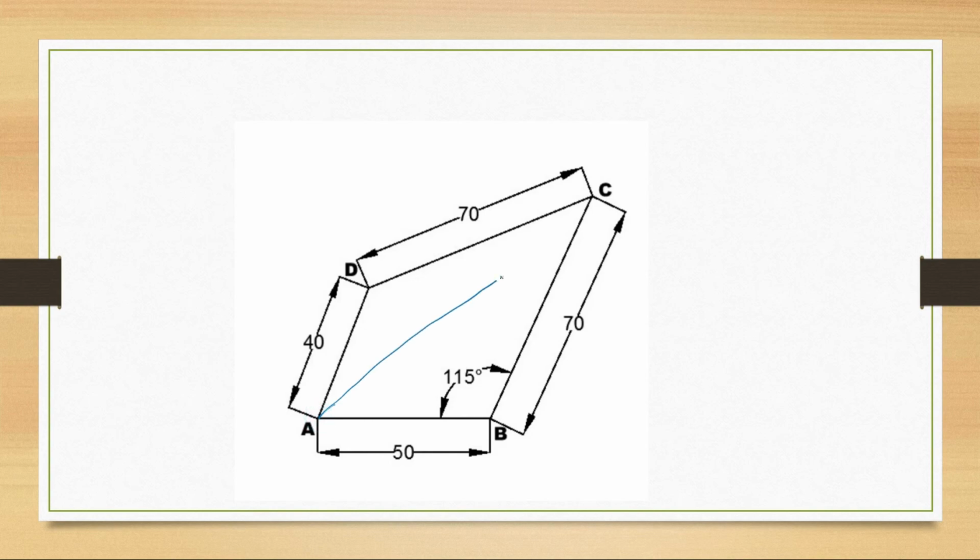So let's just draw this AC somehow like this. And this will be the other hypotenuse. Out of these two hypotenuse, just by looking, you can say AC is the longest hypotenuse, right? So you have to set your drafter aligned with AC and then shift your drafter to point D, and from D you have to draw one parallel line which goes somewhere in the space for now.